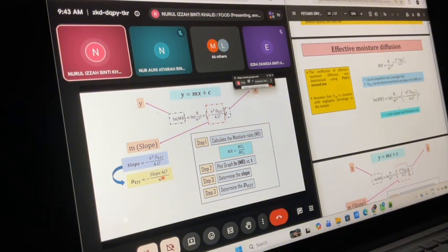You know that when the drying happens, it goes from the surface to the center. It does not involve the whole thickness. You assume that the bottom and top are both surfaces, and the middle is the deepest point. So even though they give you the thickness, the L value is half, which means if your thickness is 10 cm, the L is 5 cm.